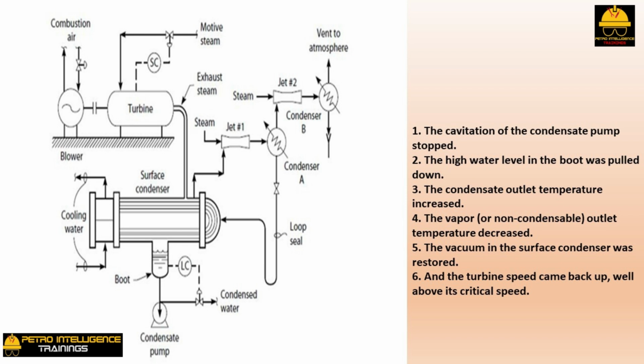The operators at the power station assured me that the problem was temporary. The normal 460 psig steam pressure would be restored by morning. Ladies and gentlemen, it is not a good idea to run a turbine with the governor speed control valve wide open. Why? Because you no longer have any speed control. And the turbine speed is then free to wander. The rest of this story is pure philosophy.